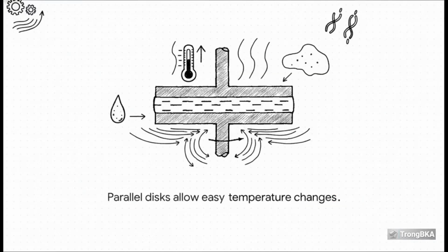Now let's contrast that cone and plate setup with the parallel disc rheometer. Here, the polymer sits between 2 flat discs. It still only needs about 1 gram of material, which is great, and it has one massive advantage. You can change the temperature really easily without having to reload the whole sample. But there's always a catch. It has a major drawback. The shear rate isn't uniform. It actually varies from 0 at the center all the way to a maximum at the outer edge. So while it's fantastic for certain tests, it's just not ideal for those complex, nonlinear studies.